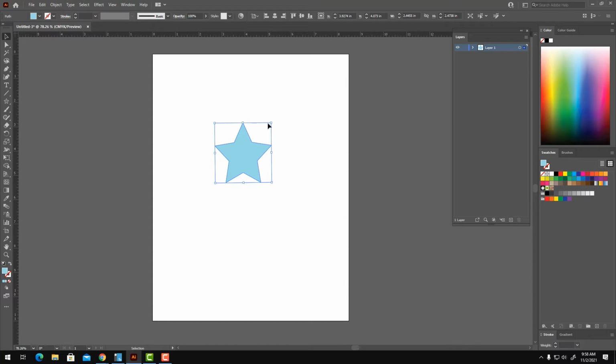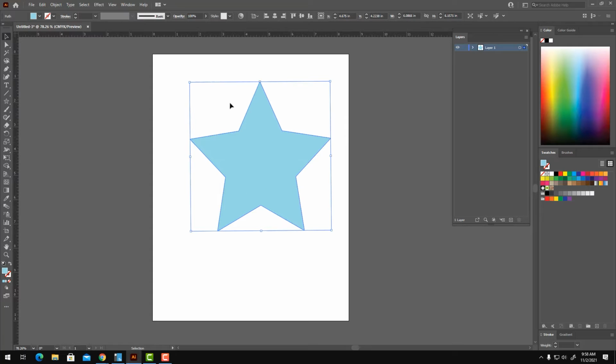That you can go here, and this will take it from the bottom left side, like so. Same with this side. Or you can do the middle, which is Shift and Alt. Hold down Shift and Alt, and then click on one of the corners, and you can see how it keeps it in constraint with a center alignment.